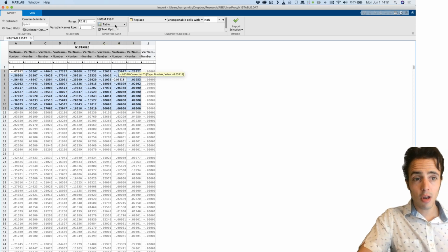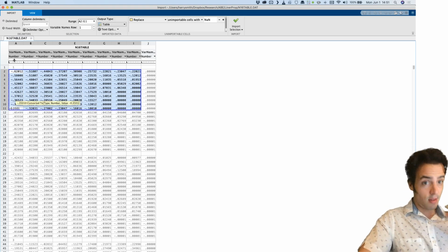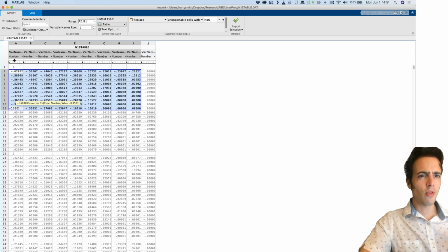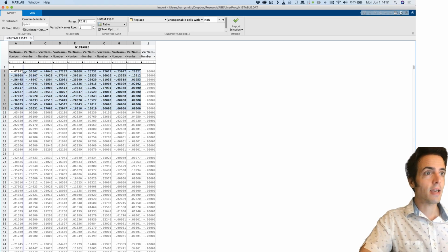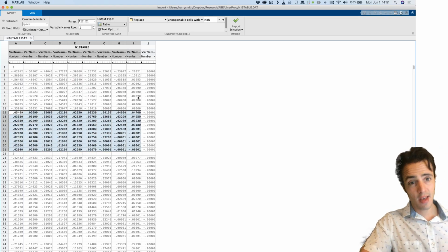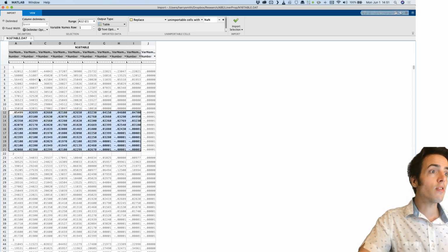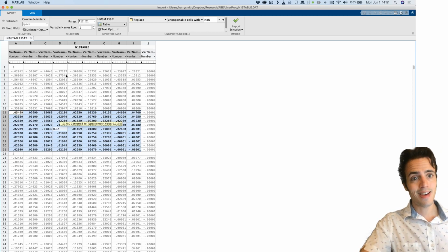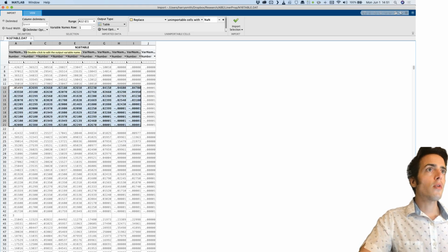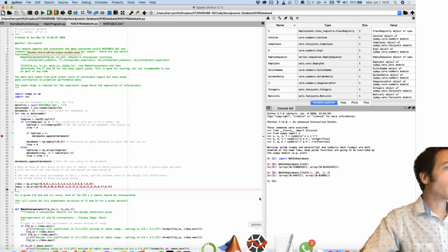Now what we've got here in the columns, we've got different thickness to chord ratios, and then down in the rows we've got different design lift coefficients, or they might be the other way around, I'm not certain. But basically everything in this block is 1 Mach number and 1 angle of attack. And then down here we've got the same Mach number, same angle of attack, we get the drag coefficient. And the variation in the two spatial ordinates in this table is design lift coefficient and thickness to chord ratio.